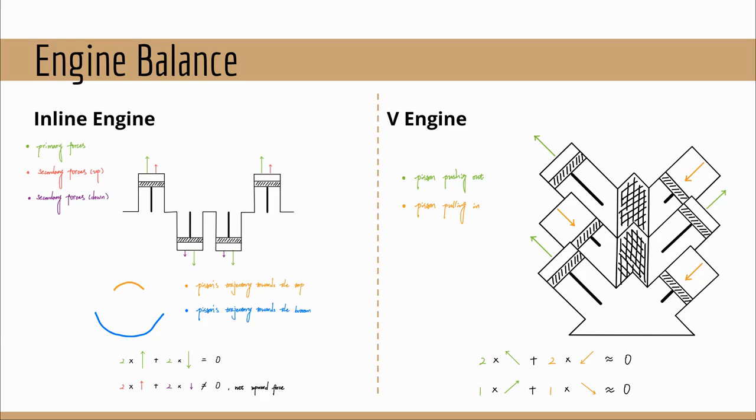The orange part is the piston trajectory moving towards the top and coming back down, versus the blue line showing the piston trajectory traveling to the bottom. We could see that the orange line is shorter than the blue line, meaning that the piston speed changes from going upwards, slowing down to zero, and coming back down in a short path, which corresponds to the change in speed, acceleration, being higher.